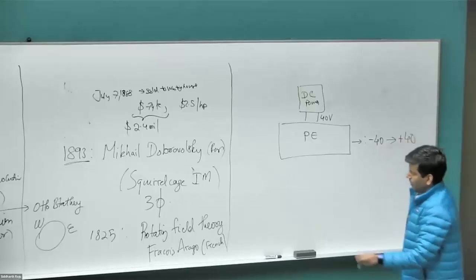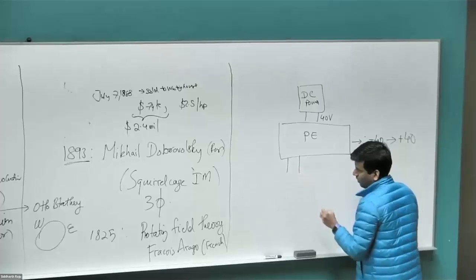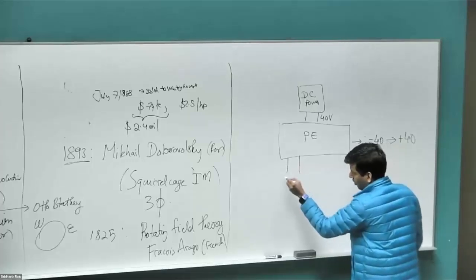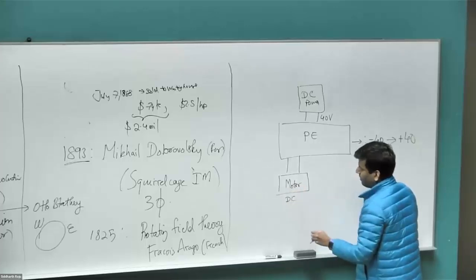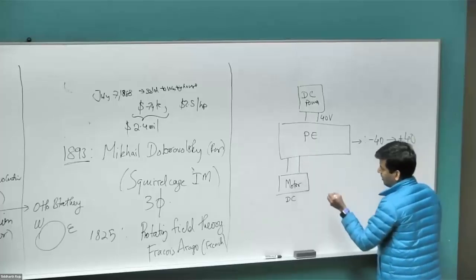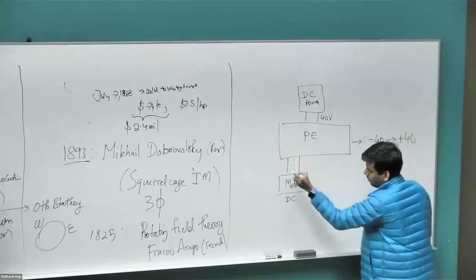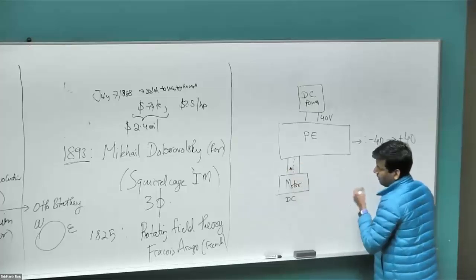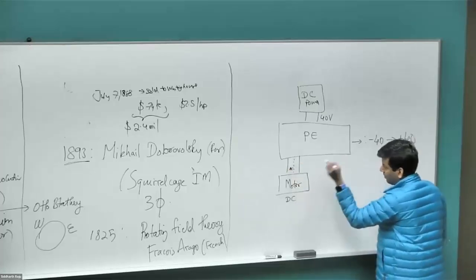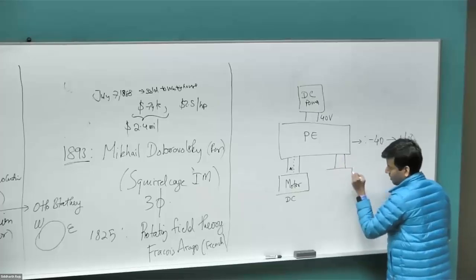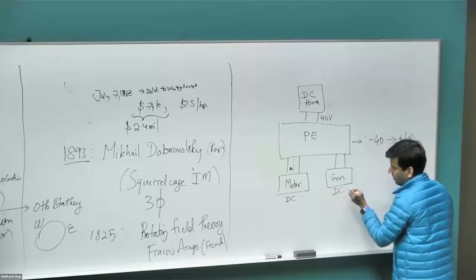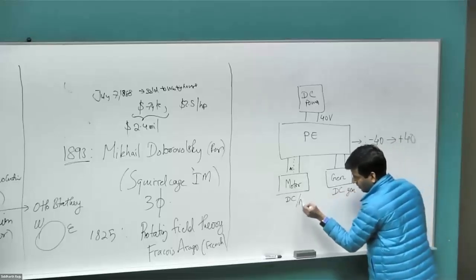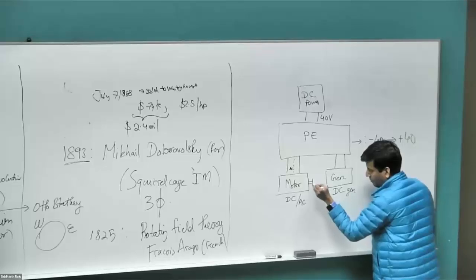Right? And there are multiple outputs coming out of this converter. I'm going to use 2 of them to connect to the motor in case of DC. And if it's an AC motor, I would use one more line, right? So let me draw that and dot it if it was AC. In AC, it will be three-phase, in DC, it will be two wires, not two-phase, right? And then we have a generator, and we are always going to be using a DC generator. And these two are mechanically coupled to one another.